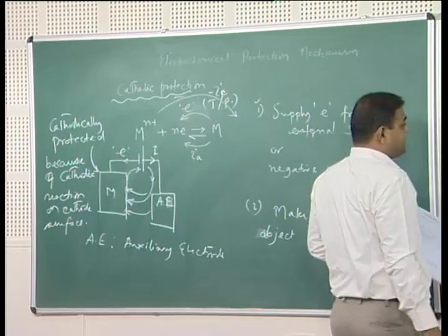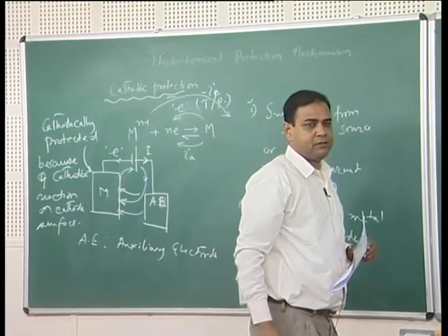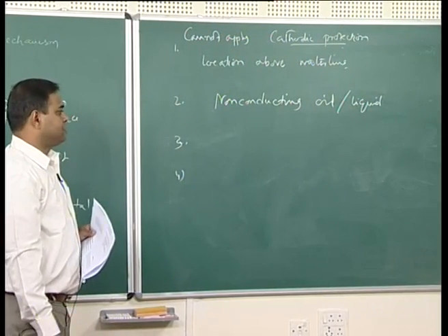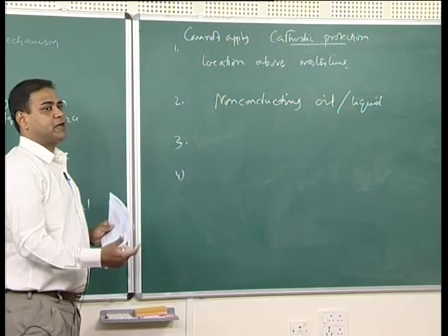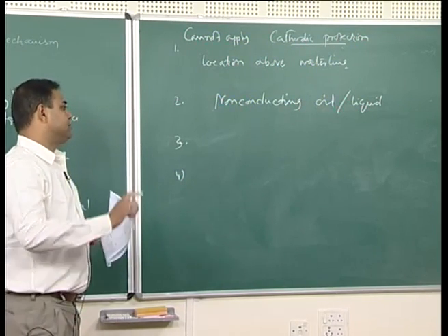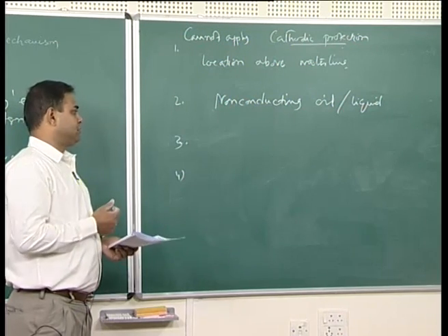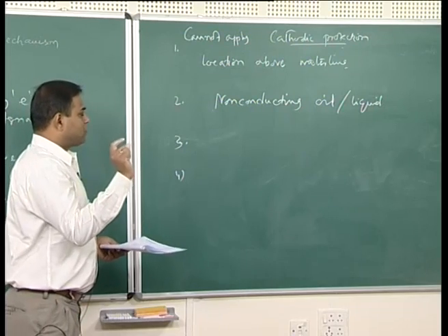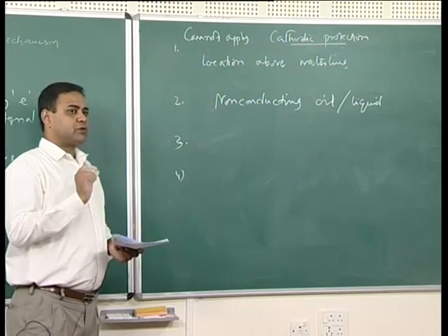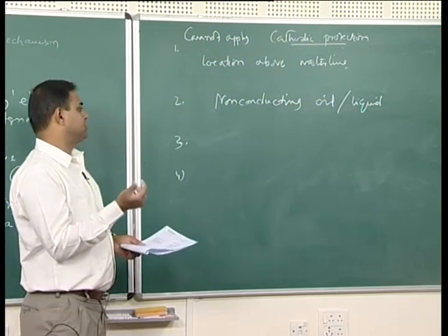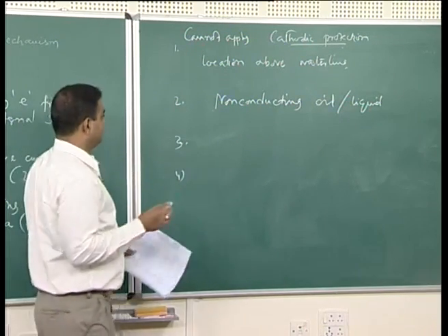If we have a screened area or shielded area, like in the example I have given in case of a water tank with a pipeline attached to that water tank, the pipeline will not be under protection because of that shielding, or because of that small metallic stopper we are using just to stop water flowing out through the pipeline.